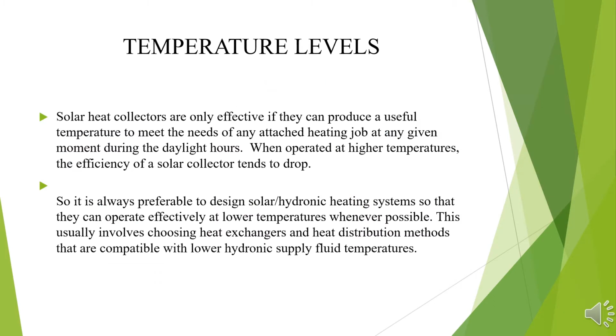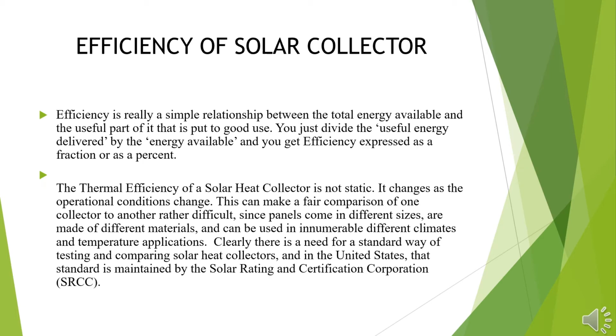About the temperature levels, solar heat collectors are only effective if they can produce a useful temperature to meet the needs of any attached heating job at any given moment during the daylight. So it's always preferable to design solar or hydronic heating systems so that they can operate effectively at lower temperature whenever possible. Efficiency of a solar collector is a relationship between the total energy available and the useful part of it that is put to good use. The thermal efficiency of a solar heat collector is not static.